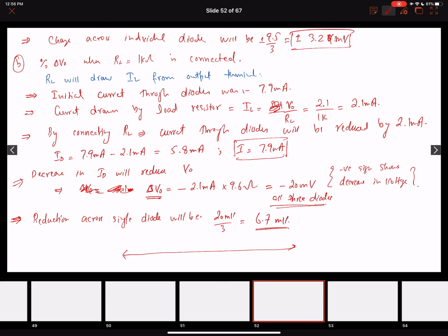We're going to build further on that and discuss another type of diode, a special diode specifically designed for voltage regulation, called a Zener diode. Another interesting thing we will see in the next lecture is that we will use Zener diodes not in the forward condition. In today's lecture examples, we used the diodes for voltage regulation in the forward bias condition. We will use the Zener diode in the reverse breakdown region, and we'll develop voltage regulator circuits that are even better in terms of voltage regulation.